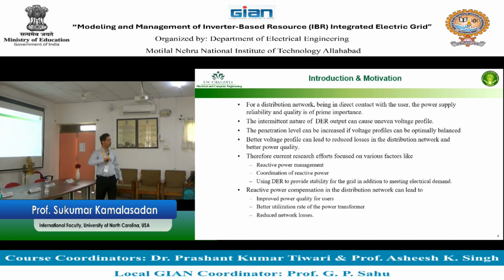Active power is not like that. If you push active power in one place, it goes all the way to wherever it can be reached, up to the load, and the load draws it, except for the active power drop, or voltage drop, as we call it. Okay, are you following? Having said that, reactive power coordination is not difficult, because reactive power coordination is only